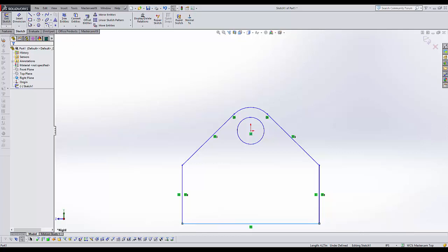Now, I have taught you to use this button here, Smart Dimension. I taught you to right button mouse click and use it here, but now we're just going to hold the right button mouse click and go upwards. Let's take a look at that again. As I hold the right button mouse click, we have some other information up here that will allow us to quick snap to that command. So let's go straight up, dimension.